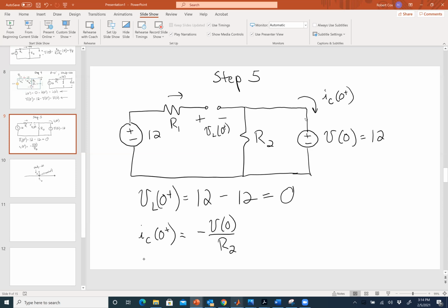Okay. Do you redraw it as an open circuit because your current source was 0 amps? That's right. Yeah. In fact, I can leave it that way. So here's 0 amps, and here's R2. Solid connection. Right. So a 0 amp current source is an open circuit. In other words, it's saying that this current source is forcing 0 current to flow through there. That's an open circuit.